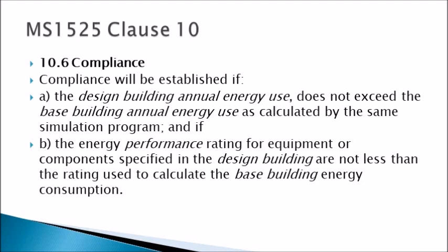That means, for example, if your shoebox hypothetical building produces a building energy intensity of 100 kilowatt hour per meter square per year, then the BEI of your actual building shall not be more than 100 kilowatt hour per meter square per year.